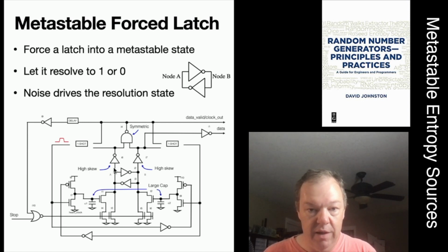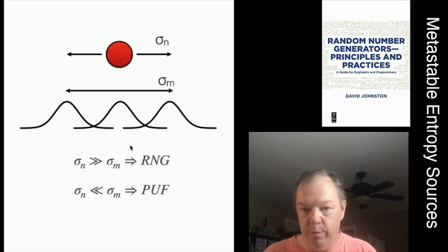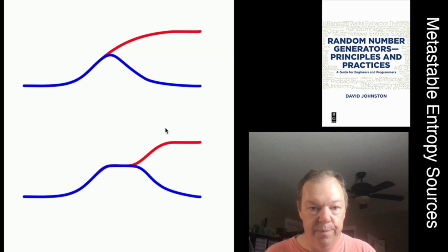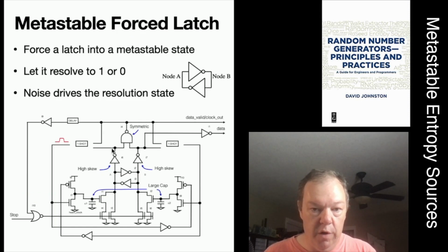So what does that mean? Go back to this. The threshold for that buffer seeing a 0 or 1 is not in the middle. It's up here somewhere. So this red is representing one half of the circuit and the blue the other half. If both of these are in the middle and the threshold for the buffer to see a 1 is above it, then it's going to see a 0 and a 0. So it'll output a 1 and a 1.